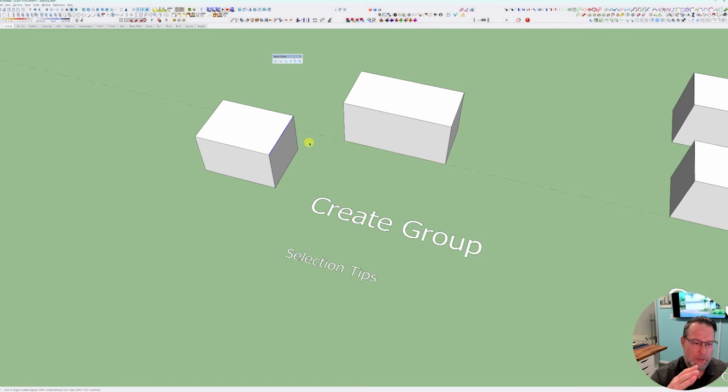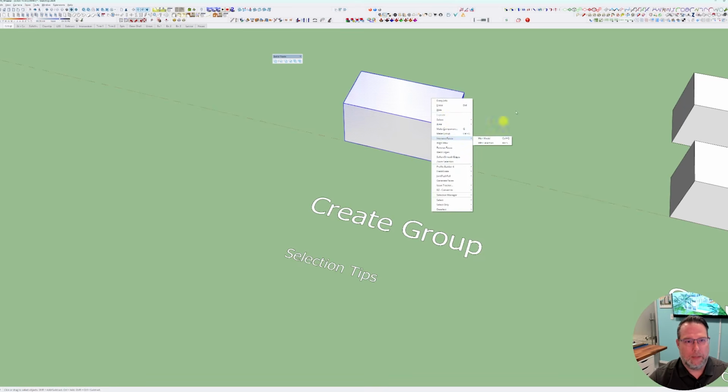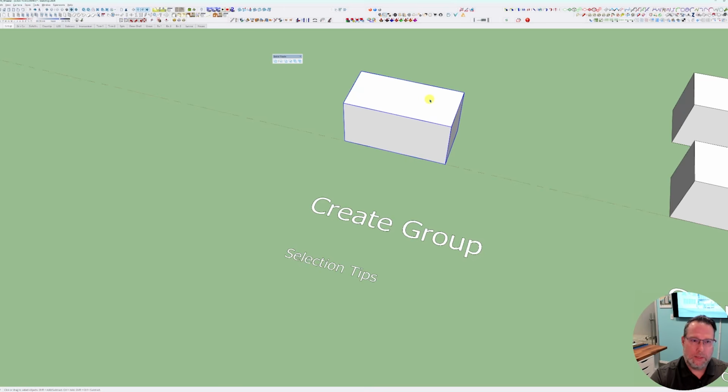At its core in SketchUp, groups are one of the most critical items. So the first thing we need to do is turn anything loose into a group. So you can do that by selecting everything, right-clicking, and going make group. If I select everything, I have Control G as a keyboard shortcut to make a group. I think using keyboard shortcuts is invaluable from a speed perspective, and I highly suggest everybody understand keyboard shortcuts, create your own keyboard shortcuts.